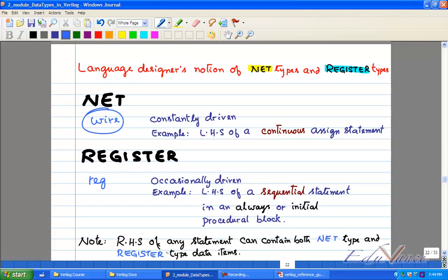हाँ. I'm just thinking, for example, let's say above 3.6 we have a 1, and below 3.6 we have a 0. Right. So if I go, let's say I get 4 volts, current, I'll create a high potential and a low potential on the other side. So it won't create. You have to assume there is a low potential on the other side. You cannot create a low potential there. You can only create your potential. Please understand that. You can only create your potential. You're assuming that there is a low potential there, or there is a potential there who you are higher than him, which is typically 5 volts. So you're giving him current, and when you want to give a 0, you'll pull yourself to ground so that you can pull all the current back. Clear?